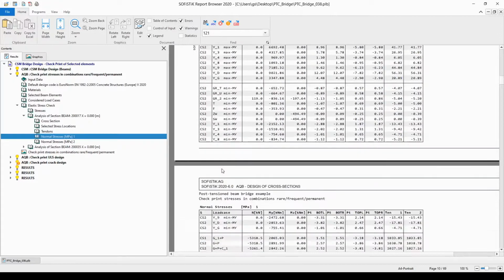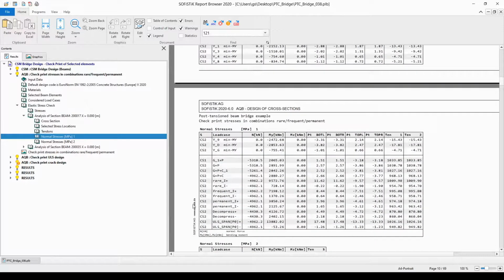If we scroll down in the output, then we are going to find some special combinations, from which the most important one is the GPC effect together. So a special combination was created to calculate the internal stresses from the total G, P and C effects. If we have the result of this special combination, we can simply superimpose the effects from the pre-superposition combinations.